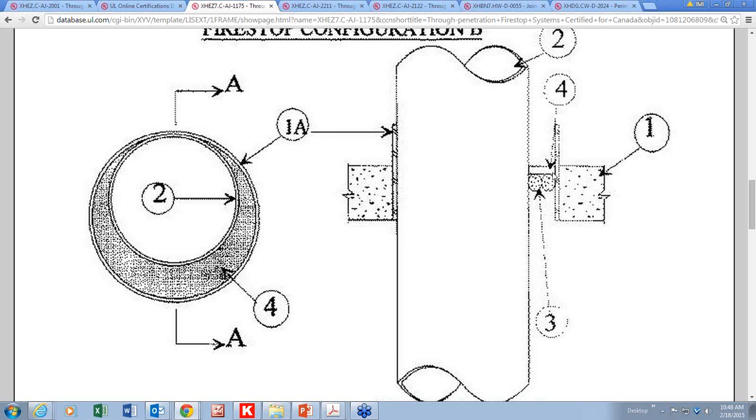Let's say it's fresh material. It's only been in for a day and a half. If it's a latex material, silicone material, or any type of Firestop sealant, there will be some shrinkage that takes place. Why? Because there's solvents or water that cures off over a period of time. So in order to really inspect it and understand if the contractor has installed it properly, a calculation has to be made to the percent solids.